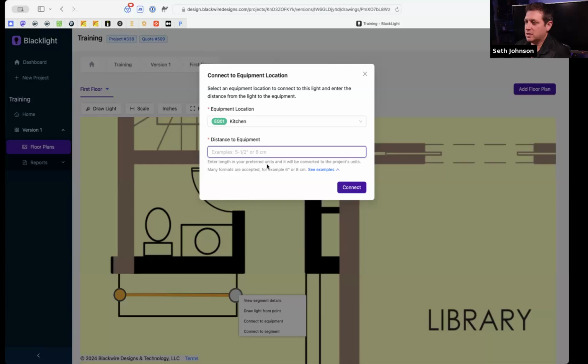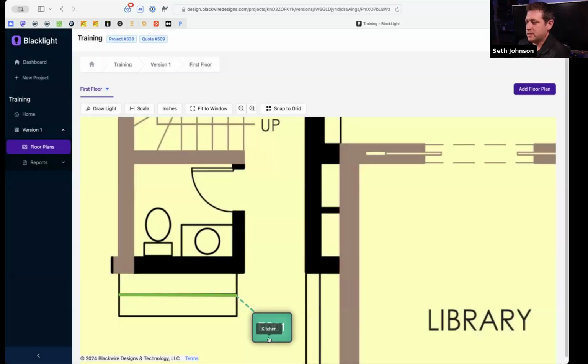So there's going to have to be a little bit of guesstimating put into this, but it's going to help determine what your wire gauge is going to the fixture. Let's just say it's roughly 8 feet away. You know, if it was in the cabinet below that you had here, or in an upper cabinet or something, it could be less, but we'll put it here.